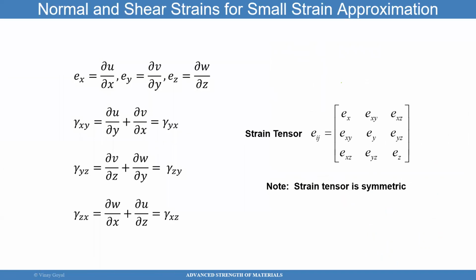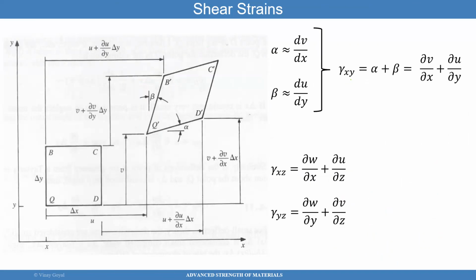The shear strain is defined as alpha plus beta. I took the alpha, added the beta to it, and that's the total change in angle starting at 90 degrees. It started at 90, but it changed by this amount. So the shear strain is a measure of distortion. You can see that happening there with my calculations.